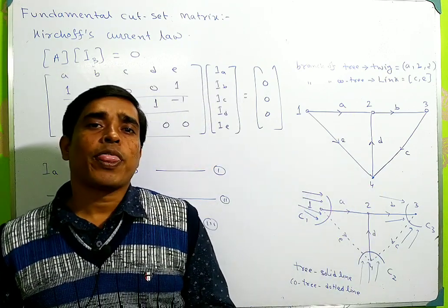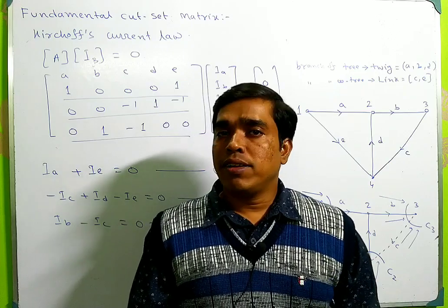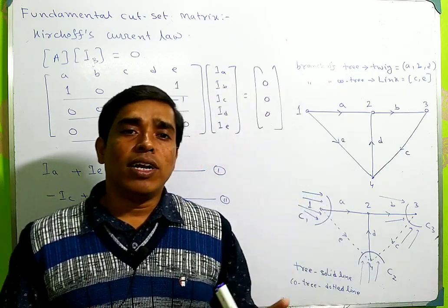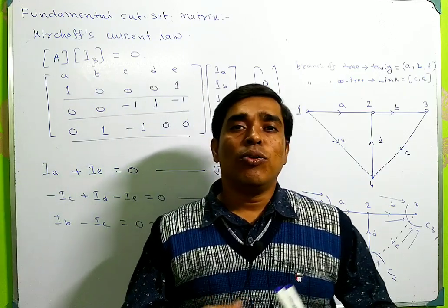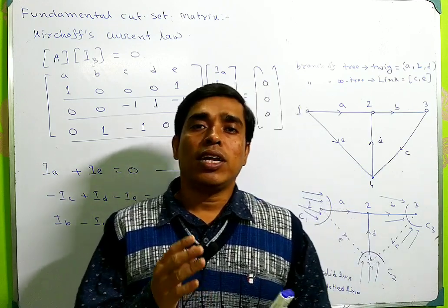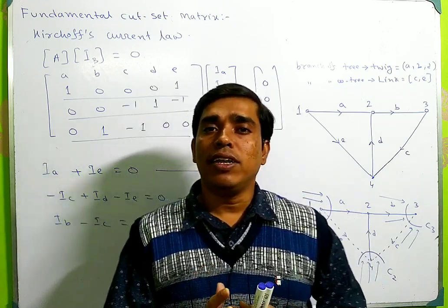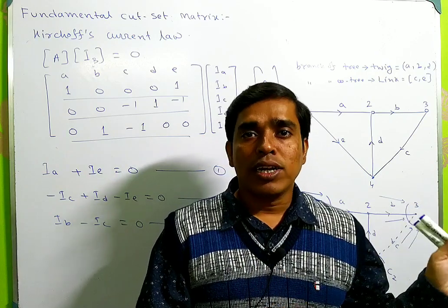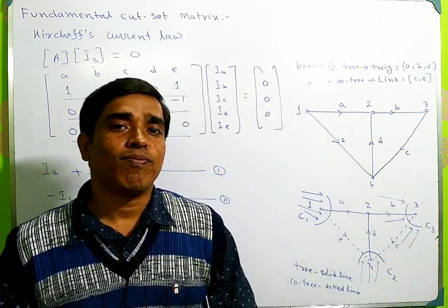So using the fundamental loop matrix and the fundamental cut set matrix we can develop the KVL equations and KCL equations of a network using graph theory.